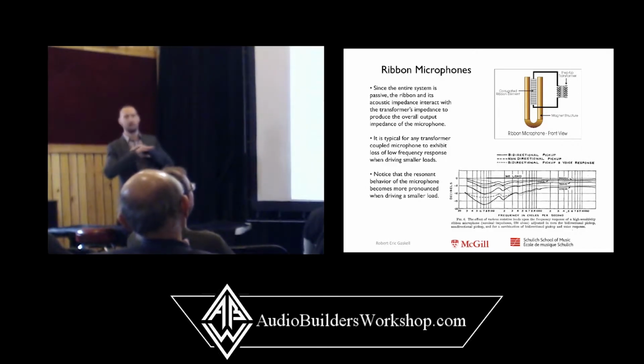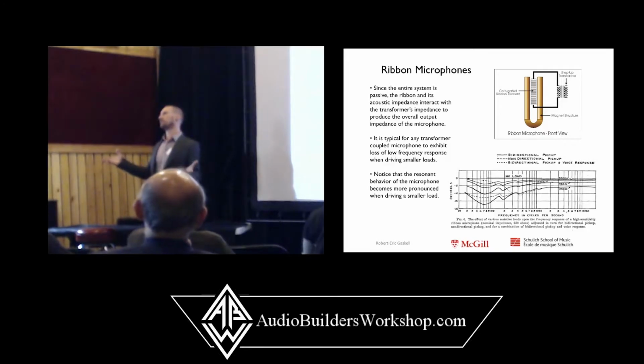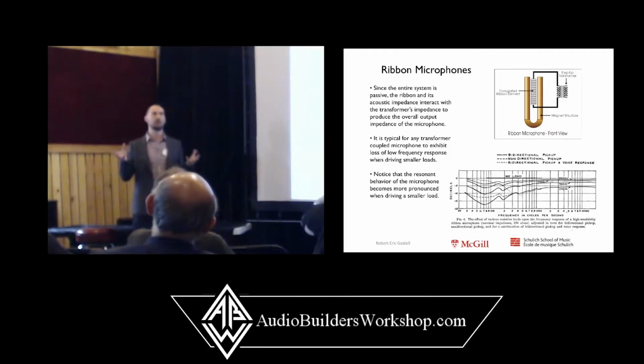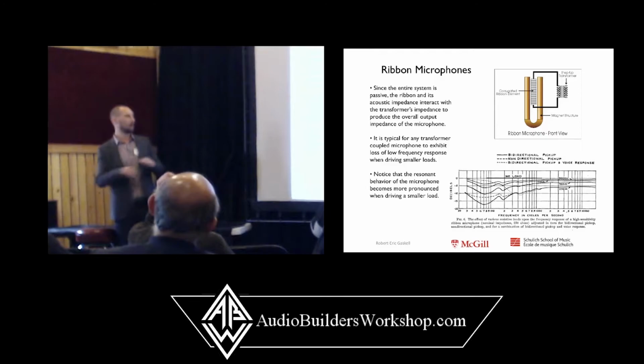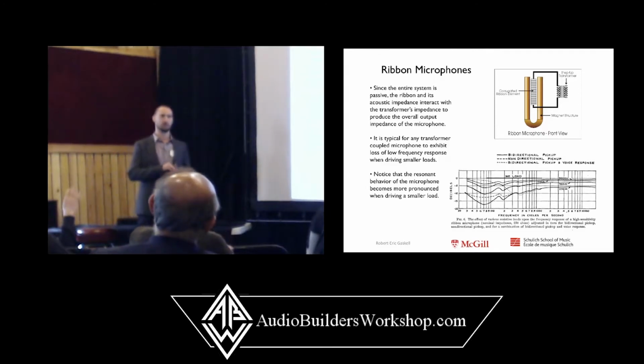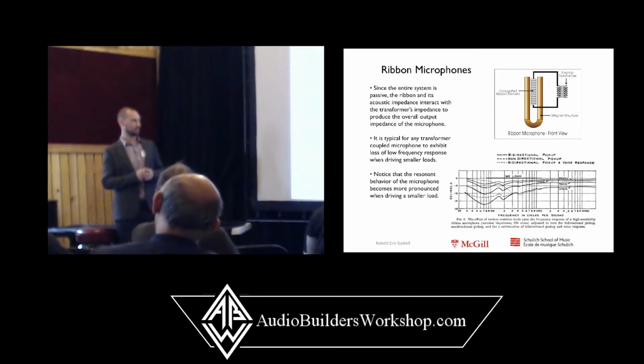That's obviously a theoretical line, not actually a measurement. But as you increase the resistance at the input of the mic pre, you get a flatter frequency response. So generally speaking, when you see mic pre's that have a ribbon mode, for example, the Grace has a ribbon mode, the AEA mic pre's are dedicated ribbon microphone preamplifiers. Typically, they have very high input impedances to give you a flatter frequency response with those types of microphones.